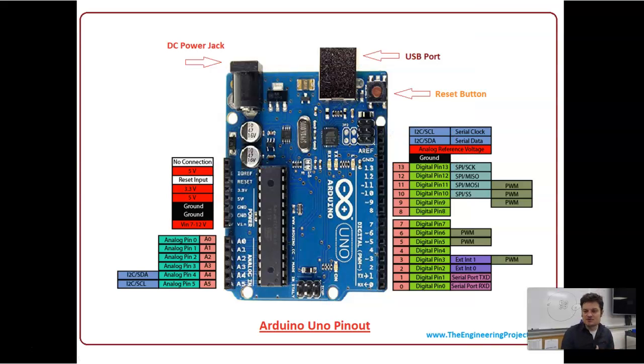This image is, again, showing us what the Arduino looks like. Again, we're using the shield, so it doesn't matter as much, but what we do care about is these ports, because we have to tell our Arduino program what ports things are plugged into. Over here you can see we have all the pins, 0 through 13.